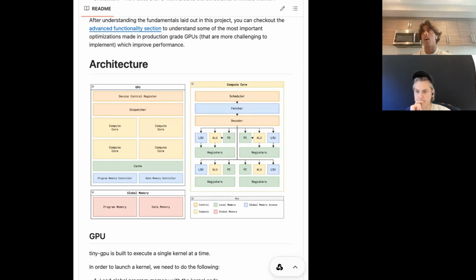So the question is, how do we manage the constraint that memory has a fixed bandwidth? Like, let's say it can only take 2 requests at once. And then all these resources are requesting memory at the same time. So you need something to actually throttle all the memory requests, and on the GPU side, hold them. So it's like, here's all of our requests. And then send them slowly to memory to respect the bandwidth that memory actually supports. And then slowly send those responses back into the individual compute units in the core.